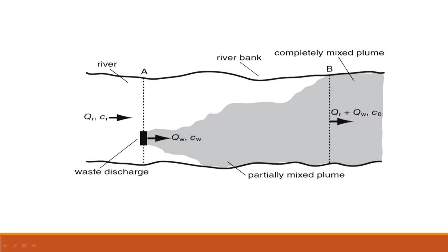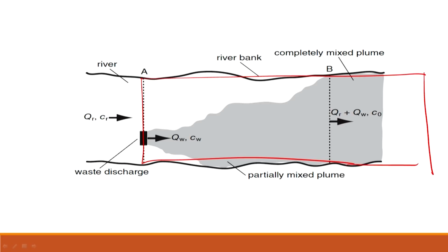I need to obviously apply a model across the relevant river, and then estimate, if I know the concentration here in Haridwar, what will be the concentration in Roorkee. So for that again I need a control volume, which is my river. I need the mass flux coming in, mass flux going out. I need to know the reactions occurring in the system. Typically I use a symbol for reactions occurring, but that can sometimes be misleading. Please do take a note of that.